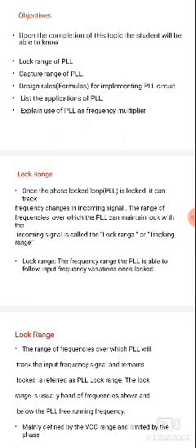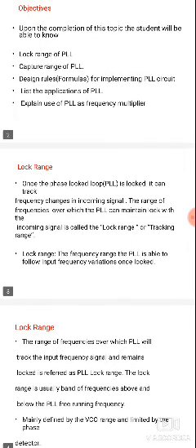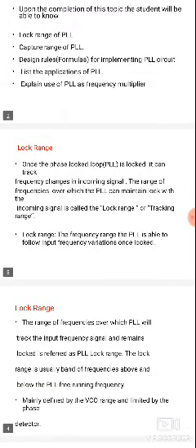In the PLL block diagram, the input is the phase detector or phase comparator, and the output is the VCO. VCO is nothing but a voltage controlled oscillator. So there is a direct connection from the VCO to the phase detector.